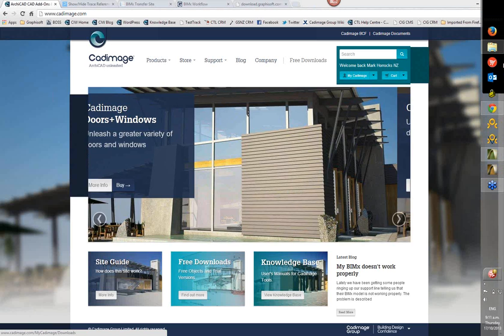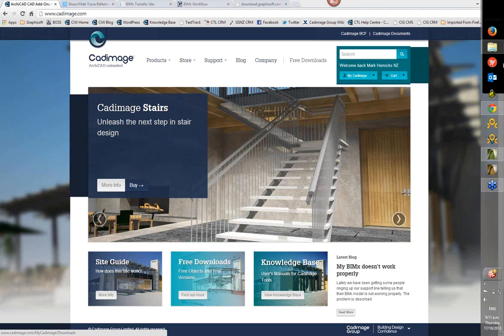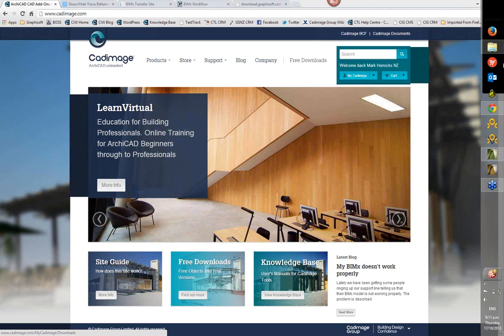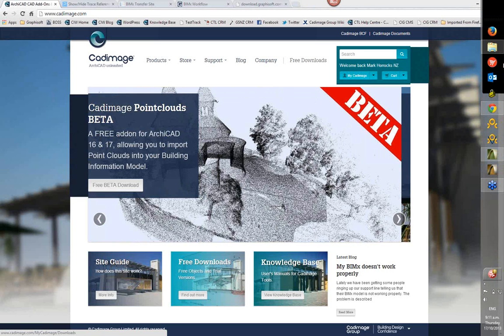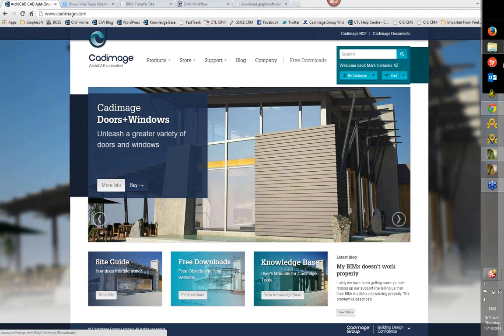Consolidate Libraries works from 13 to 16 automatically. Once again, hitting the Consolidate button. They do have migration libraries for 10, 11 and 12 that are installed with ArchiCAD 17, but they require a link process.